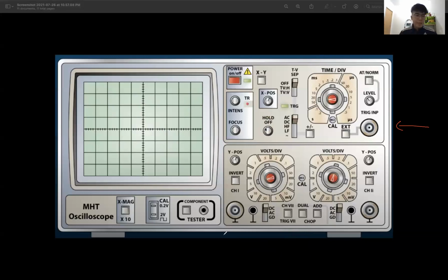Okay, so we talk about measuring current with the CRO. What do we use it to measure? Measure alternating current, right? Okay, when you measure, you connect the input to the Y plate. Let's say I want to measure the current from a battery. I connect the input into which one? The Y plate. The gain, okay? The gain. The time base I switch on.